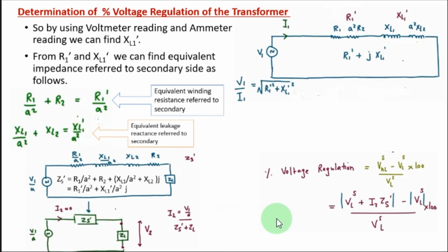So when you connect a load, this is the value, the voltage across the load. The no load value means the addition of these two, and minus VLS, which is the voltage when the load is connected, and VLS same here, and then the percentage. To take the percentage, you multiply it by 100. So this parameter is called the voltage regulation.